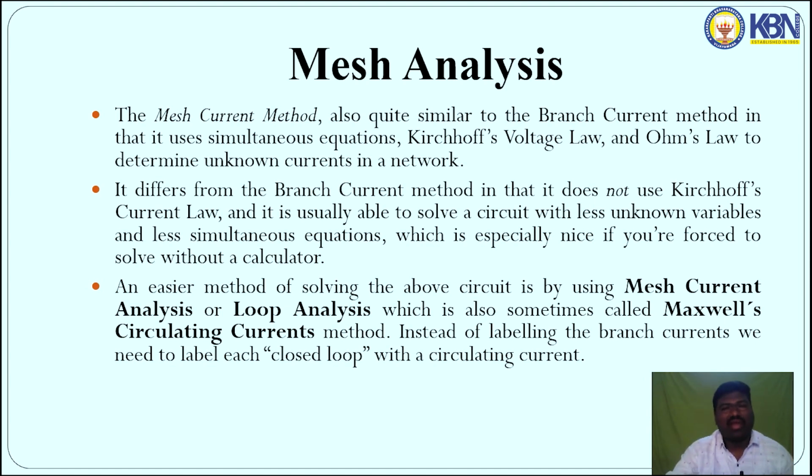It differs from the branch current method in that it does not use Kirchhoff current law, and it is usually able to solve the circuit with fewer unknown variables and fewer simultaneous equations, which is especially nice if we are forced to solve without a calculator.